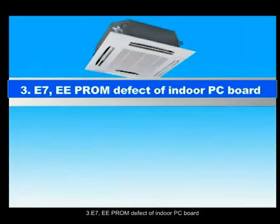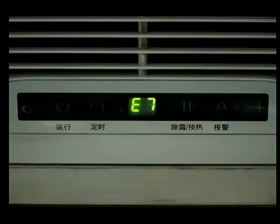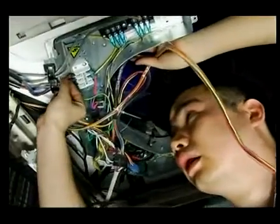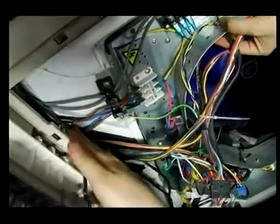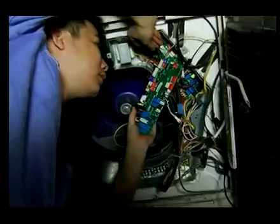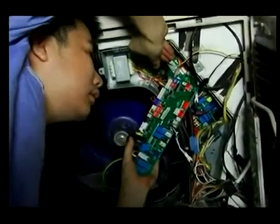3. E7, EEPROM. Defect of indoor PC board. Repair instructions when E7 appears. Check if the electric control wiring is reliable or there is strong interference around indoor units. If so, try to keep away from the interference. If not, you may change the indoor main control board.